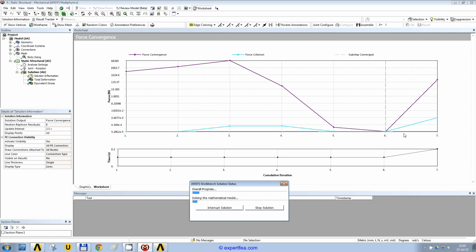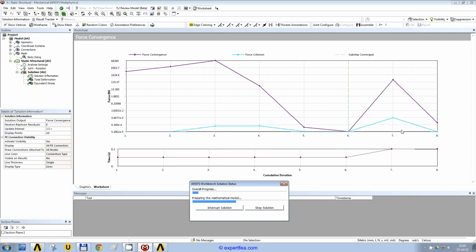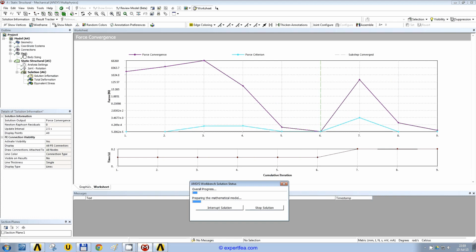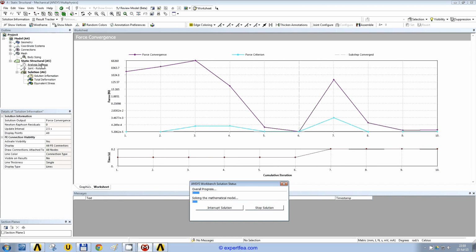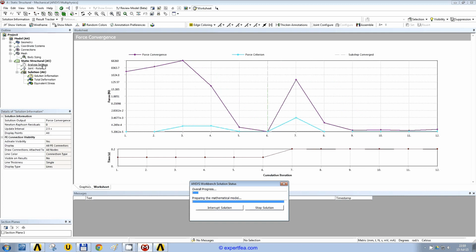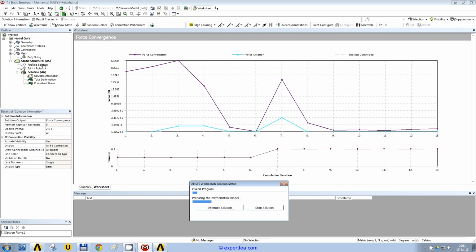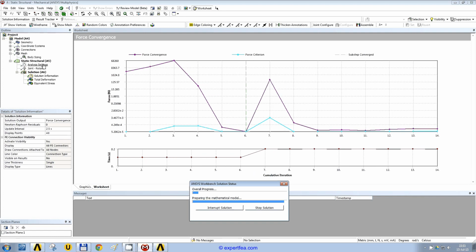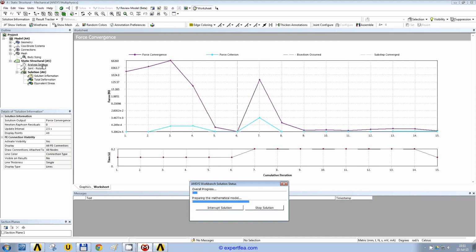And we achieved the convergence from the beginning. So what we need to remember is that we either adjust the mesh size, or adjust the time step. We have a bisection now.